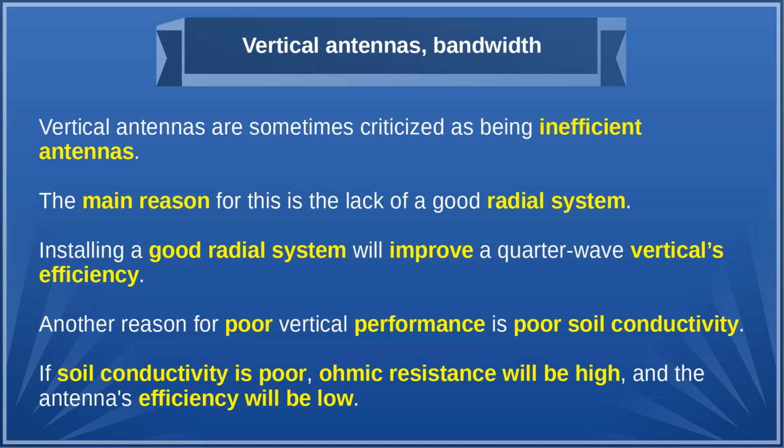But radials don't have to go in a straight line. They can wiggle. What you're trying to do is create a ground plane, a reflective plane. And the more of them you have, the less holes you have in there, so it looks more like a solid piece of copper, or water. It's the same as your dipole antenna, it doesn't have to go in a straight line, it can zigzag around. Your direction may change, but it'll still function quite well, and you can match it.